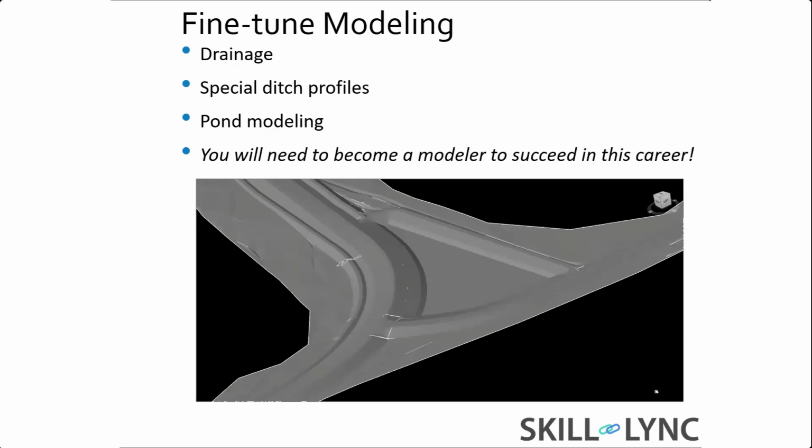currently. And again, if you are realigning the road, you're going to have to put in a pond. All that water that you're treating has to go into the pond. So these are things you're going to have to do. You're going to do pond modeling, special ditch profiles, and as you see there in italics, to be successful in this career, you really have to be a modeler.